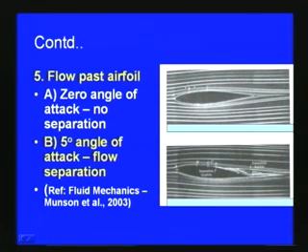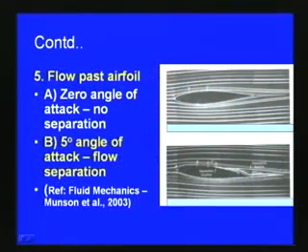This is the case for 0 angle of attack, but if you slightly tilt the same airfoil so that some angle is formed, for example 5 degrees of angle of attack, then you can see that the boundary layer will be of a totally different nature, and flow separation also takes place. In the second figure, taken from Fluid Mechanics by Munson, the separation point is here, and there is even a possibility of a small wake formation for this airfoil case.